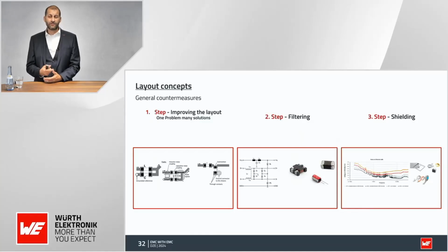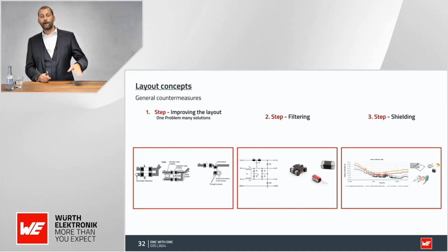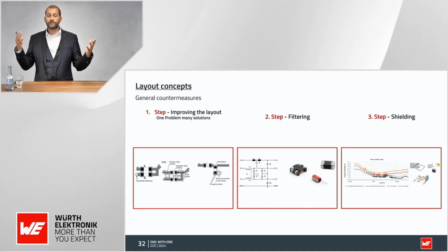And the second problem is that shielding is really expensive. And I don't mean the actual components, but the additional manual labor. Attaching copper tapes or aluminum tapes onto your casing or your connectors is most often manual labor. Manual labor costs a lot. We try, at least in our layout step, to reduce the amount of THT products and use more SMD products. And with shielding, we increase the costs dramatically.